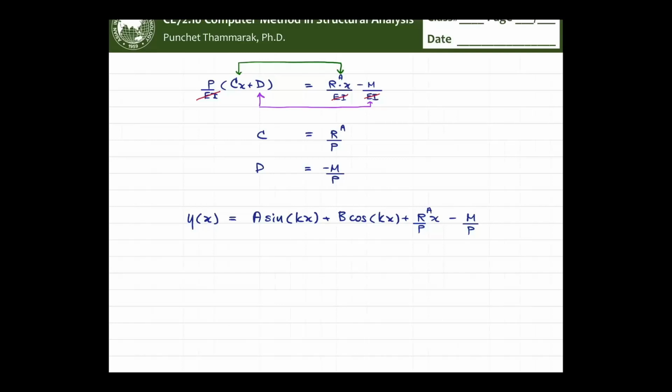Then you look at the M over P. For M over P, moment is the force scale multiplied by the length scale, divided by the P force scale, so you end up with the length scale. So that makes perfect sense. RA is a reaction force and P is also a force. They cancel, you get just the x, and x is in the length scale, right?